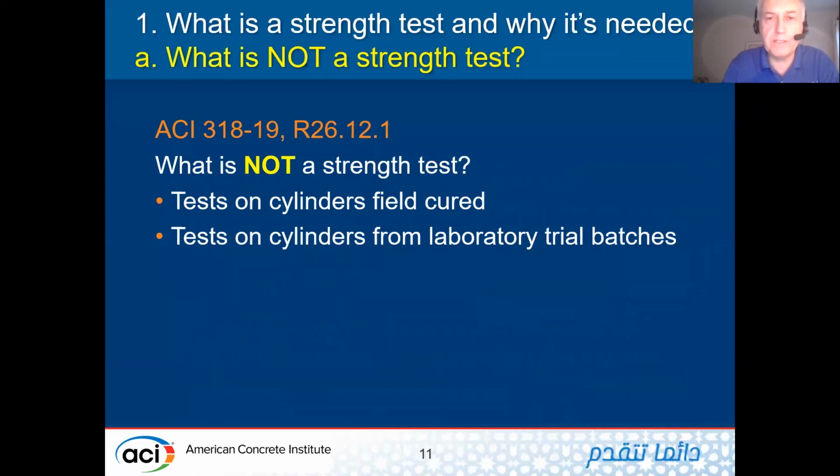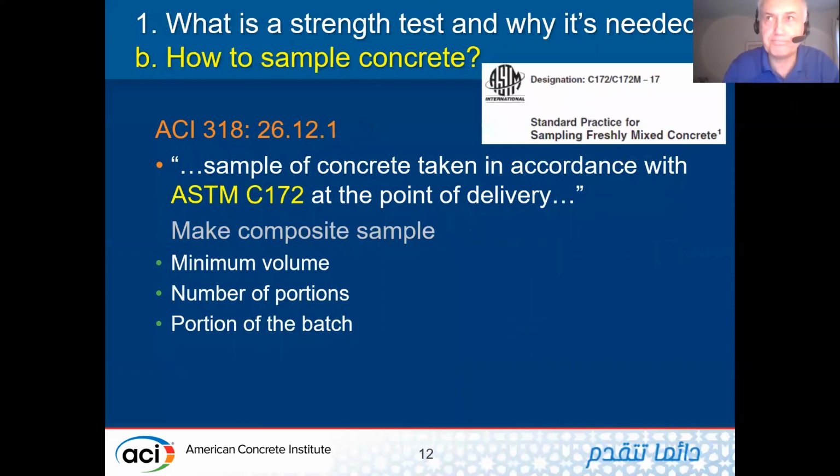Before doing that, let's define those things. What is not a strength test? When you do the test on cylinders that are not field cured, or cylinders that are made from laboratory trial batches, they are not considered a strength test. Again, you'll get strength values, strength breaks, but they are not considered in the language of ACI 318 or 301 a strength test.